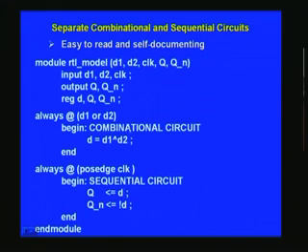It is a good practice to have this. And this does nothing more than take the exclusive OR of two inputs and assign it to D, and that is what this logic is doing. This is just a D input for a flip flop, and the flip flop is written in a segregated block here, which is also an always block, and the action is taken at the positive edge of the clock.